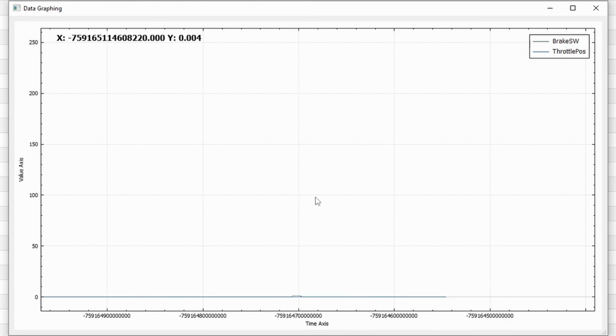I'm going to go full throttle in 3, 2, 1. Full throttle. There we go. And we're up to the line, 250. Now I'm going to go kind of partial throttle, mid-throttle, and just kind of hold it there. Okay, holding, holding, holding. Then I'm going to go completely off the throttle, back to 0. Boom, there you go. So, the value of 250 makes no sense when we're talking about throttle percentage. Throttle percentage is 0 to 100. You can't have a 250% full throttle. It might make us go faster, but you can't do it.